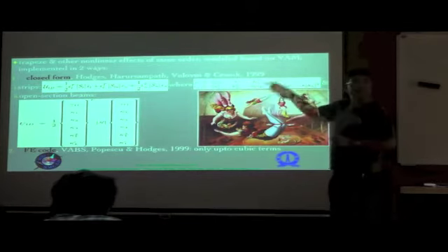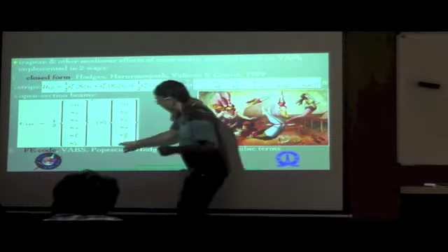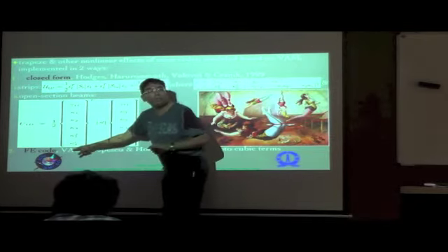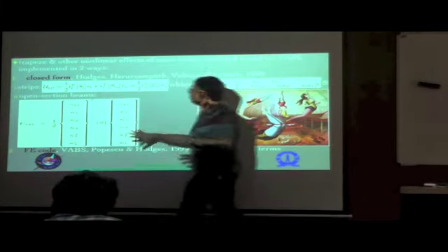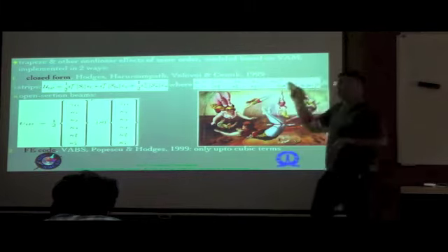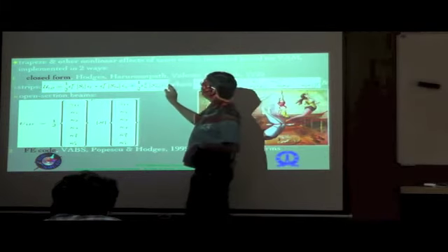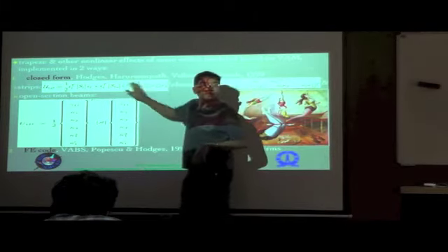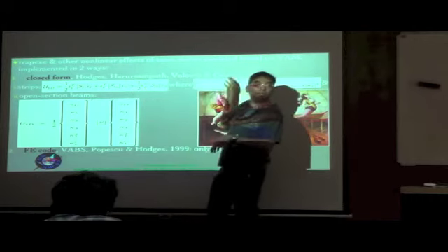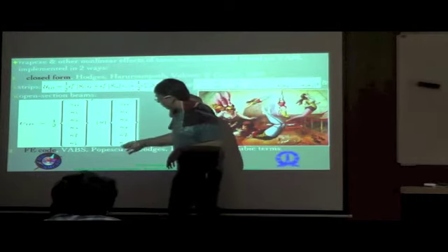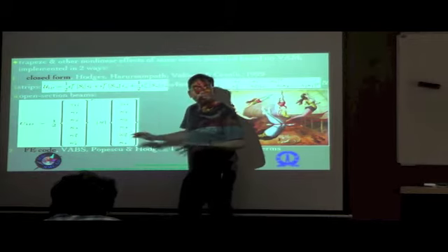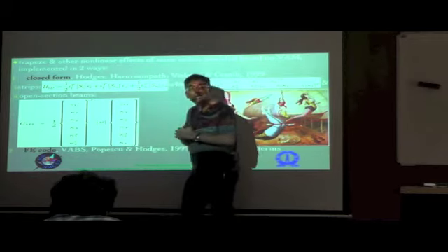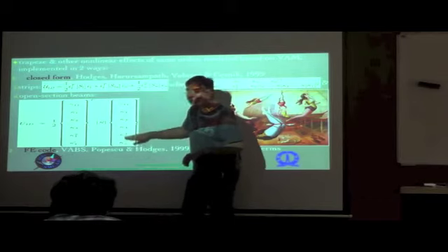But you get an additional term which was not present here, which is basically this particular kappa 1 prime term, which comes because of the restrained warping effect, which is a higher order effect here. Not that it is not present here, but it is not as important as these two terms. It would come as a much higher order term, whereas here it comes out as a term which is of equal significance in terms of asymptotical correctness, equal significance as the nonlinear term.